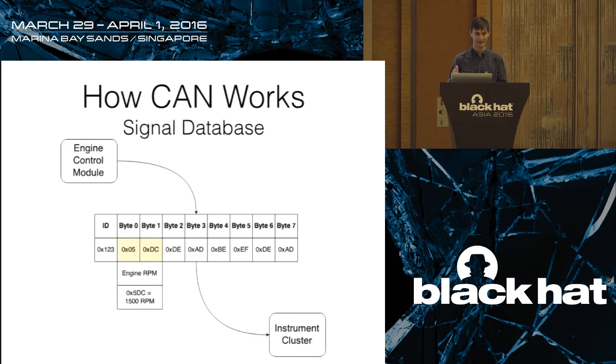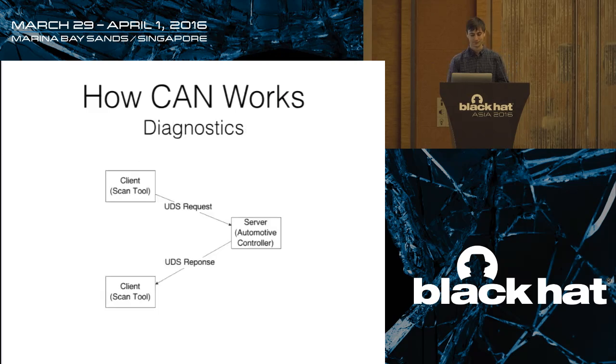They're all defined at the time where you design the system, and then the software that's actually running on the controllers has this statically set up. There's another way that CAN is used, and this is not a day-to-day thing, but it's definitely true of any vehicle you have. Absolutely any vehicle made past 1991 is going to have some form of diagnostics. It was first mandated solely for emissions purposes by the California Air Resources Board, who actually have led a lot of innovation in automotive.